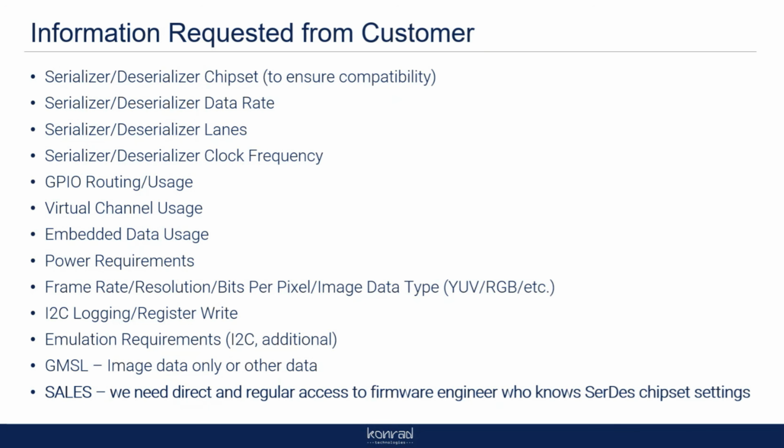The other thing that's interesting is we need to be able to know on their ECU, is the ECU happy? Because from the camera perspective, it's a little bit easier, because can we see a valid image? Yes. But if we're passing the image on in tap mode, or if we're trying to generate data to send to the ECU, is there a command we can run? Is there something we can get back from the ECU, some sort of query? Is there a CAN status? Is there anything we can see to say the ECU is happy?